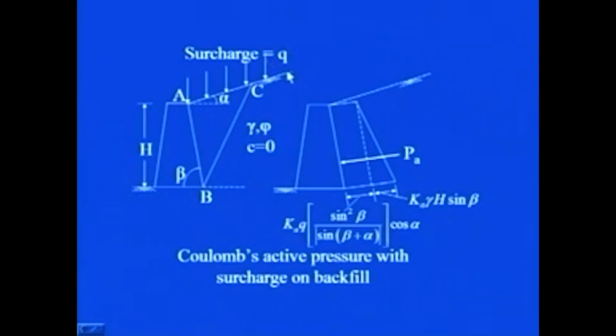Then the surcharge Q. As you have seen, how we calculate lateral earth pressure is that we calculate the vertical stress at any particular level, we multiply that by the coefficient of earth pressure and simply we get the lateral earth pressure.